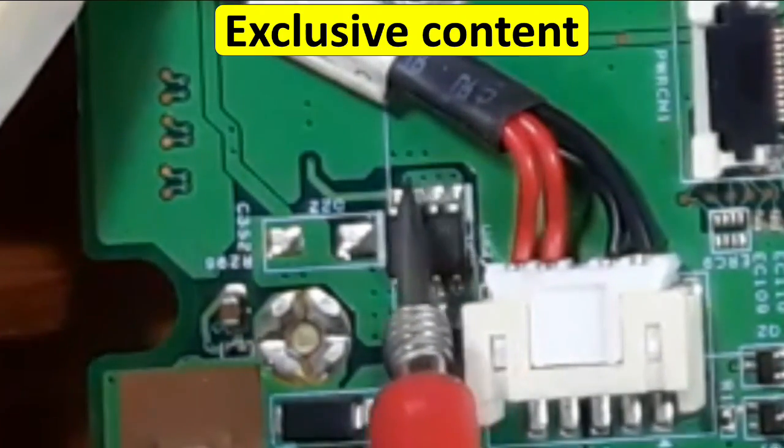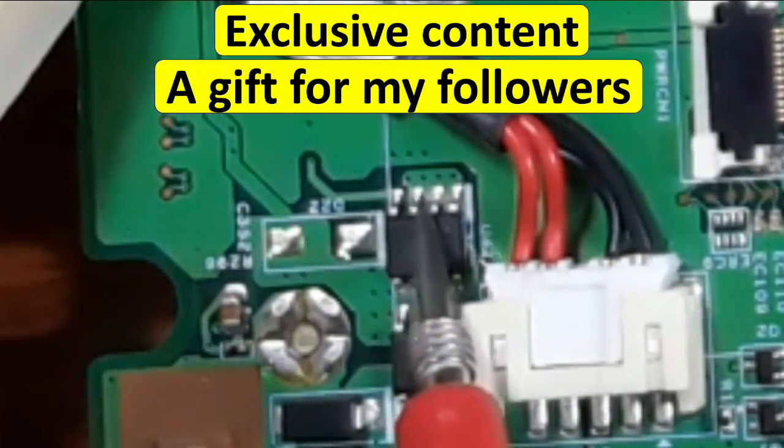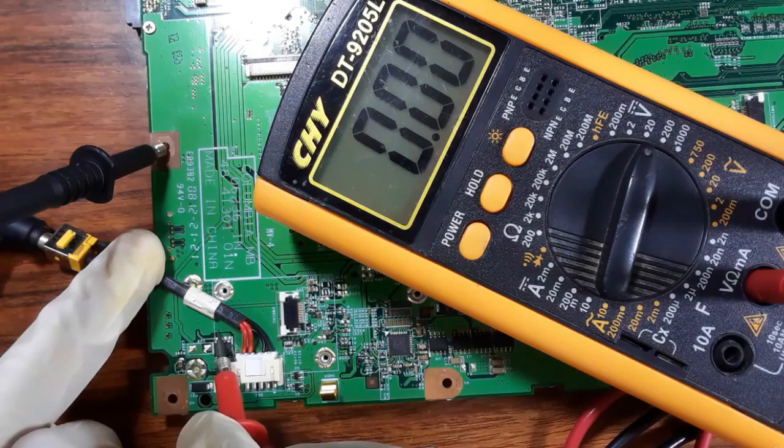We have here these points. These points mean that from here the 19 volts goes to 1, 2, 3, 4, 5, 6 to 7 places in the motherboard. So let's check where this 19 volt goes.